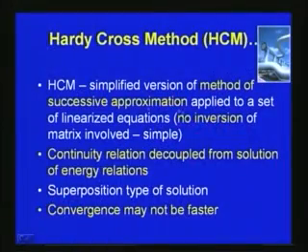Actually, the Hardy-Cross method is also a type of method of successive approximation, but it is applied to a set of linearized equations, so that there is no inversion of matrix involved. Here we use the linearized form of the equations which we discussed earlier, and the continuity relation is decoupled from the solution of energy relations. Also, we can superpose the solution with respect to the loop.